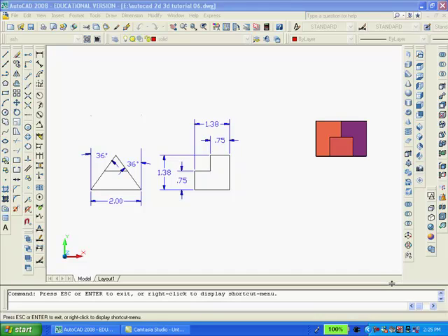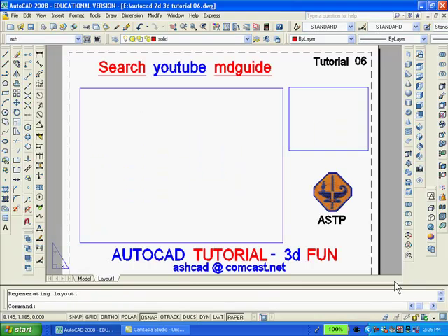Having finished the 2D solid model and dimensioning of the object, I want to get back to Paperspace to view the drawings properly and make the drawings ready for printing, so I'll click the Layout 1 button. As you can see, my template rectangles are still there. Now to create the two viewports, I'll type MVIEW, enter, and select two diagonal intersections to create the larger and smaller viewports.